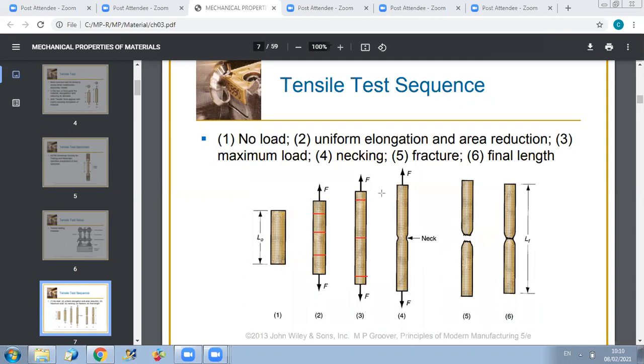In the necking part, what will happen is we'll have formation of a certain geometry which is similar to the neck. In this case, instead of the whole specimen supporting the force F to undergo elongation, the whole deformation will take place now in a very limited zone, the necking part. So we will have a drastic decrease in this area, which will lead to rupture at the end.